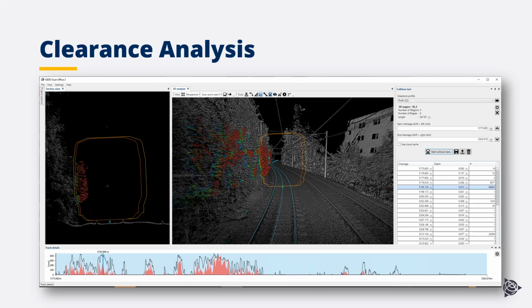With the dynamic clearance, as you can see, the train envelope is extended depending on the curvature, with extensions, or throats, in the middle and at the end, depending on the length of the wagon, so of course we get much better answers on a collision.